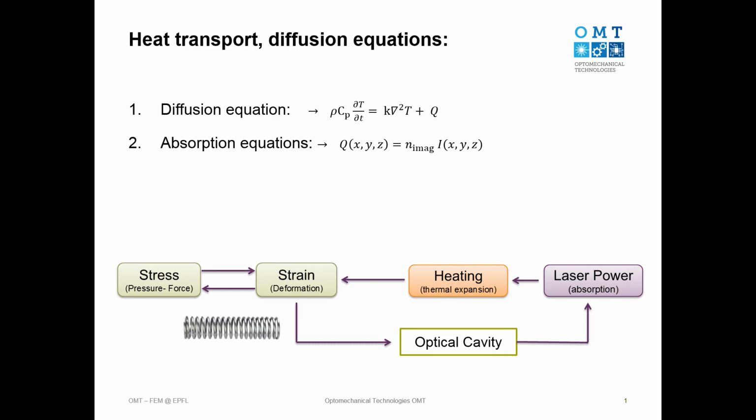Obviously, we know that there is a time constant and the materials cannot respond infinitely fast, but that's a little bit beyond this talk, so let's just move forward. In mechanics, I told you the parameters that we need to set, which were Young's modulus, Poisson ratio, and density.